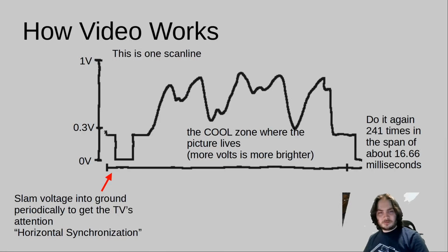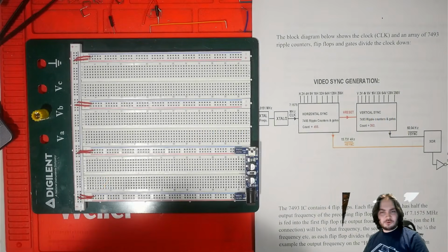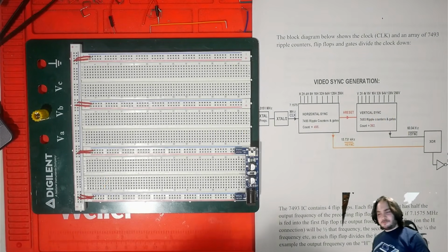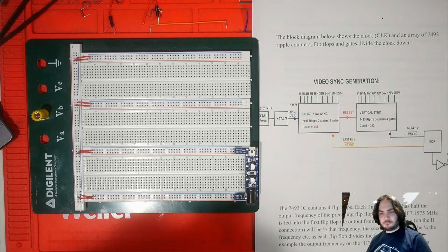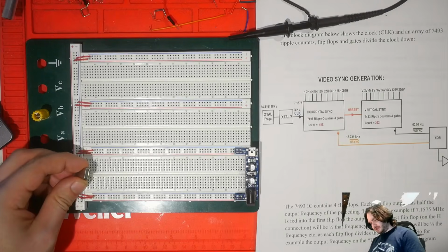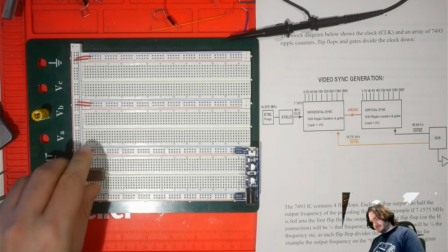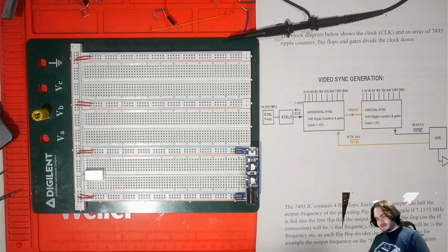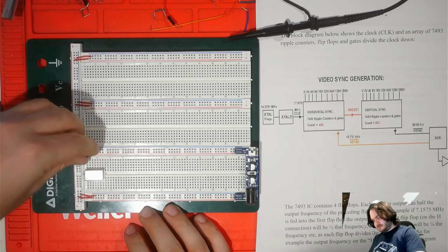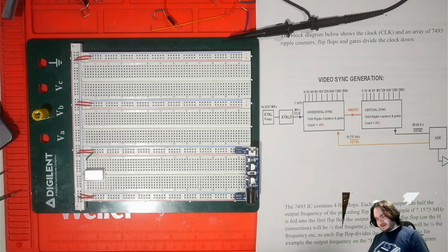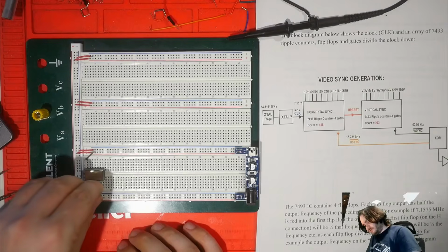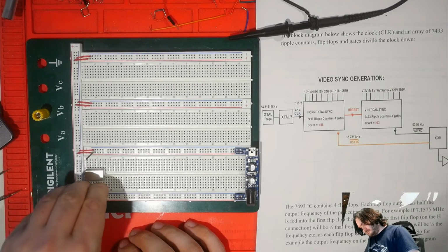I'm going to switch back now to the breadboard view again. And I'm just going to get started on plopping some chips down, and I'm going to explain every chip as I go. We'll start off with our 28.636363 repeating main oscillator, and as we saw before in the slides, we can hook up its power at this corner to 5 volts, and pin this corner to ground.